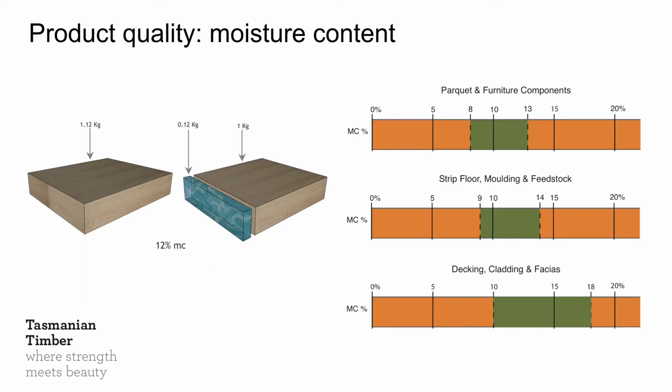There is one major technical point I want to bring up, because I mentioned earlier about how the racks got smaller over time. Okay, so wood, when it is in the tree, has a moisture content. The highest one I've seen is about 180%. What that means is that for every 1 kilogram of dry wood fibre, there's 1.8 kilograms of water in it. That was from a very wet site. So that's fine for the tree, but it's not very good for us.